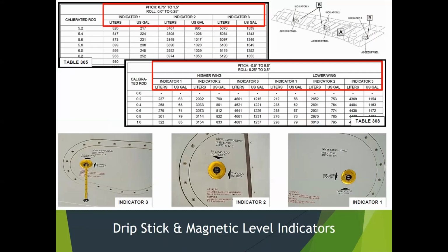What do we use to measure density of a liquid? A hydrometer. Okay. Who remembers where you saw a hydrometer? Not in the lab where I talked about this already. What class did you use a hydrometer in, guys and gals? Electrical, to do what? You test battery acid with a hydrometer. You check your acid to water mix, the ratio, because that density changes.